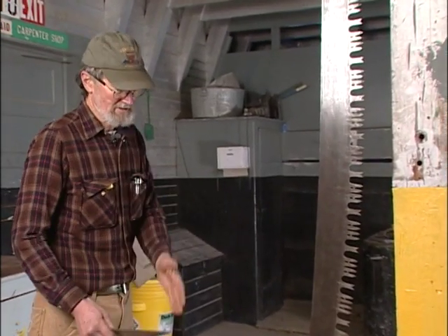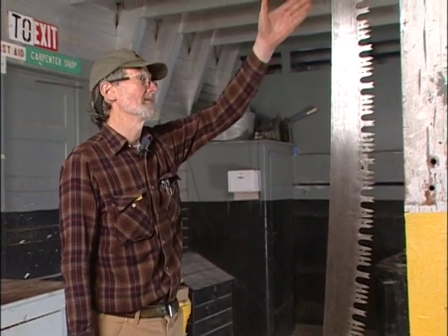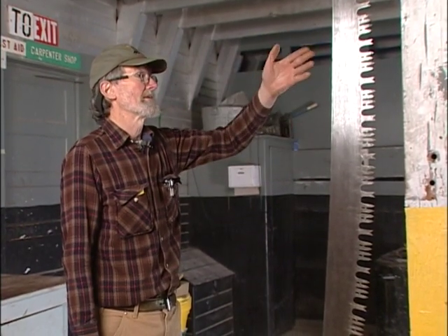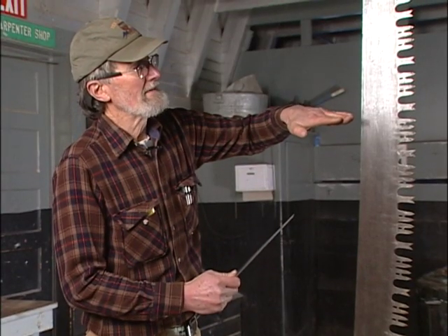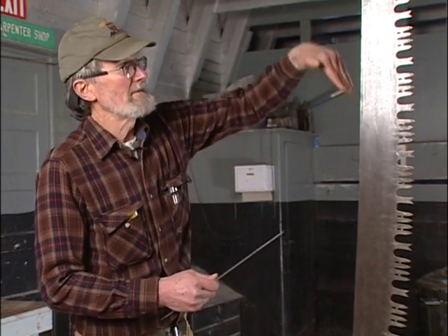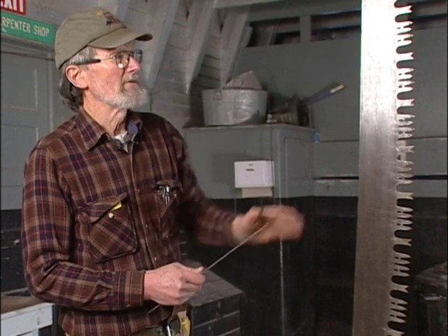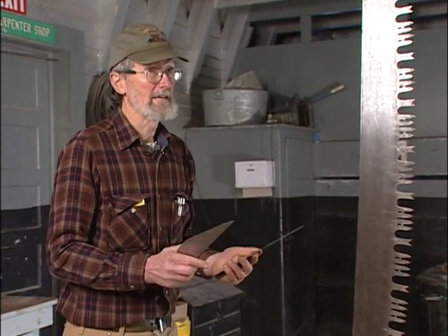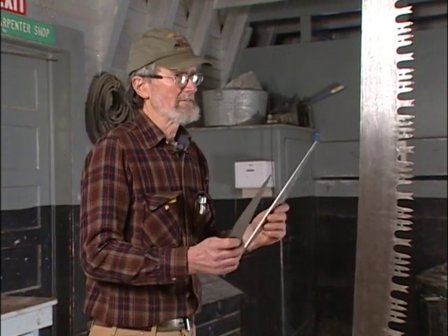Now, when I was looking straight down the saw, as I did previously, I had a pretty good idea that there was something serious going on in this part of the saw right here. But I don't know for sure what the shape of it is. I can see what the shape is on the back of it, but it's a possibility that the kink or the bow in it is not going straight across the saw. It may be diagonally to the saw in one direction or another. And the only way of really seeing that is by putting a set of straight edges on it.